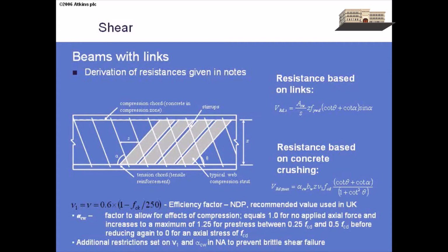The other thing you'll notice, as somebody pointed out here before we started, is that the Eurocode allows you to incline your shear links as well. And you can get some further economy out of inclining shear links. And the optimum angle is having them inclined over at 45 degrees. But don't do this for bridge works, because it's thoroughly impractical to construct, because you end up with links poking through construction joints, which isn't really very practical. And unless you can fabricate everything in one piece and concrete it in one piece, it's a nightmare for construction joints. So vertical links, I think, please still.